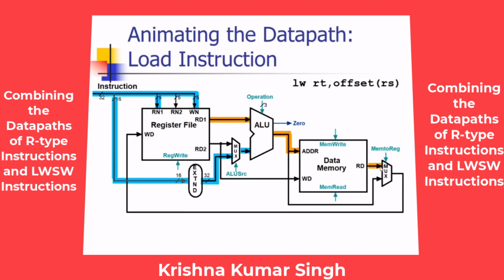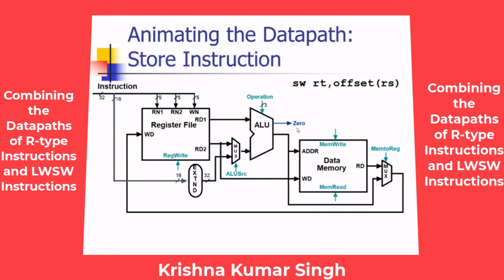Then this result will be given to the memory module, and the content of that memory address will be read. It is given to the second multiplexer, so MemtoReg should be 1 here, because we are going to select this input and put it on the output of the multiplexer. It then comes back and is written back inside the register file. Let me show you again. ALUSource should be 1 and MemtoReg should be 1 for the load word instruction.